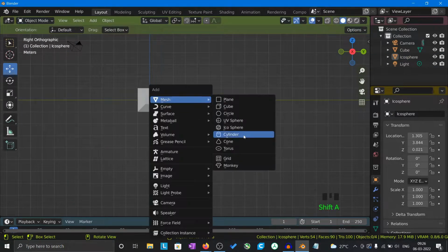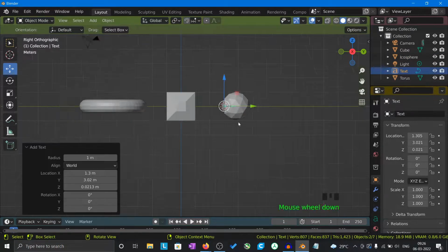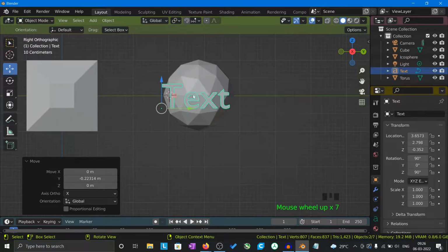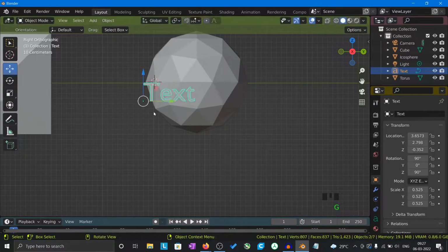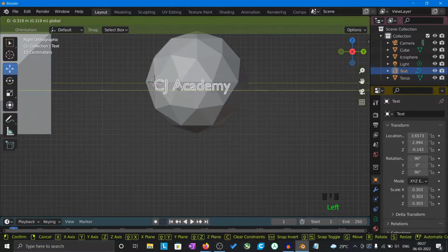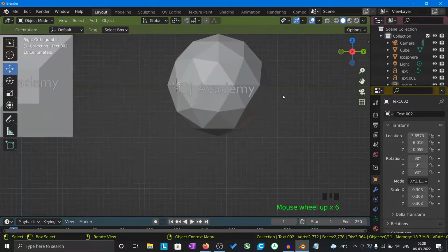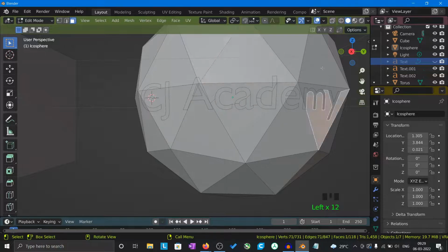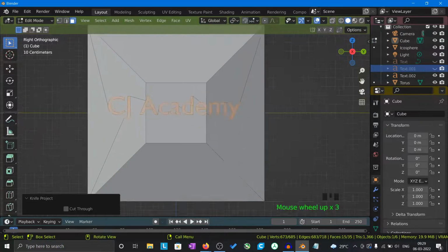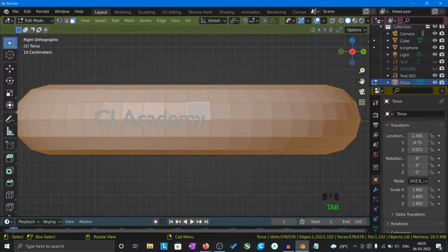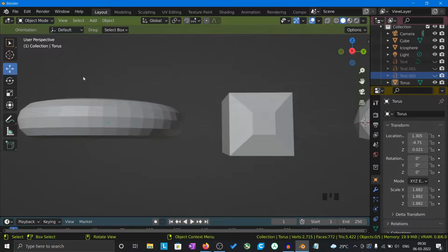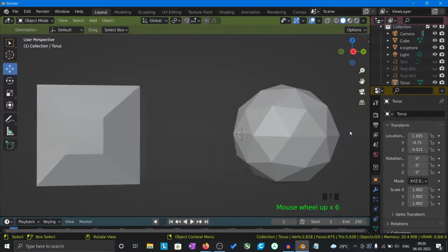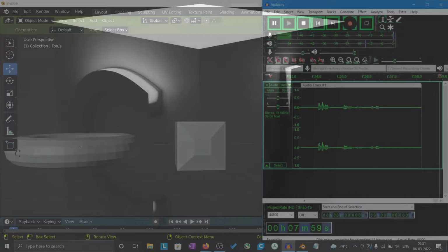If you want to project some curve on a nonlinear surface, or you want to add some text on a nonlinear surface, we have an option in Blender. It's called Knife Project. This helps you to add or reuse the curves of a text or a drawing or a curve which you have, and it will project on the surface. This especially works well on a nonlinear surface. Let's check how it works.